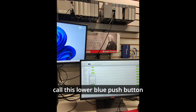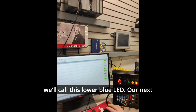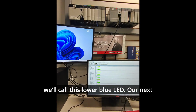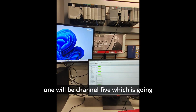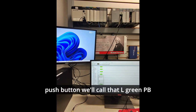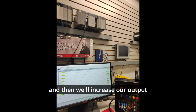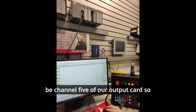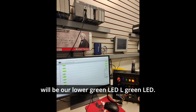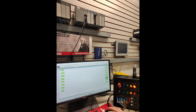Call this lower blue push button. We'll call this lower blue LED. Our next one will be channel 5, which is going to be our lower green push button. We'll call that L green PB. And then we'll increase our output address by 1. So it'll be channel 5 of our output card. So again, channel 5, and our output card is in slot 2. So this will be our lower green LED, L green LED.